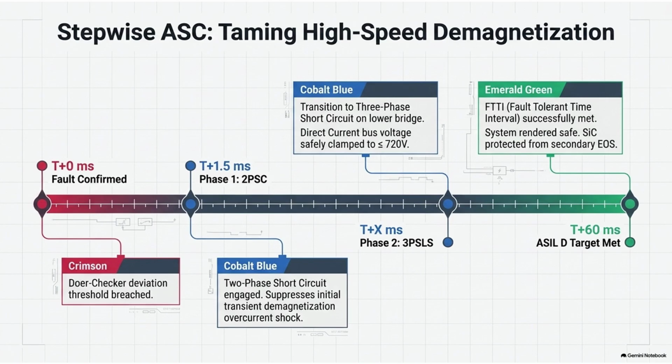And the dual error detection aspect means that if a massive radiation strike manages to flip 2 bits simultaneously within the same word, the overlapping parity bits will flag an uncorrectable state, allowing the system to instantly trigger a safe fallback rather than acting on corrupted data. Right. Now, the final key design mandate addresses the massive electromagnetic interference from the silicon carbide transistors. Symmetrical shielding. The specification requires high-density twisted cables with a braided shield coverage of 85% or greater.